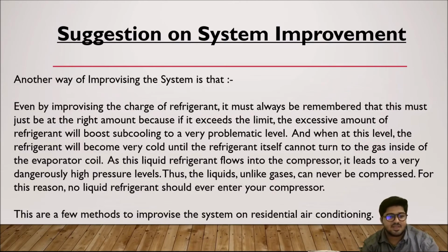Another way of improving the system: even when improving the refrigerant charge, it must always be remembered that this must be at the right amount, because if it exceeds the limit, the excessive amount of refrigerant will boost subcooling to a very problematic level. At this level, the refrigerant will become so cold that it cannot turn to gas inside the evaporator coil.